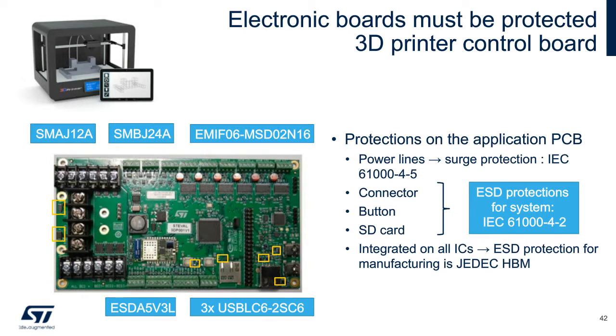In addition, there are several ESD protection devices on the board. ESDA5V3L is used for the user button. EMIF06 is protecting the SD card slot, also including the EMI filter. And finally, the USBLC6 protection devices are used for all three USB connectors populated on the PCB.